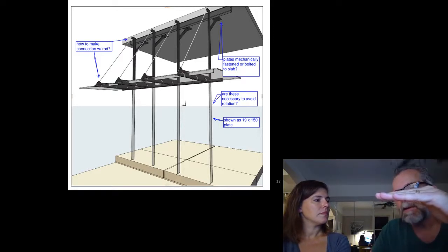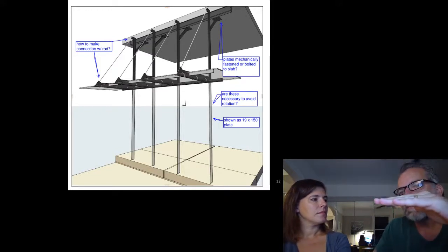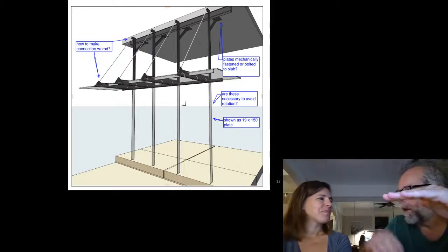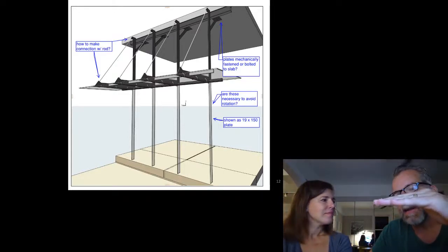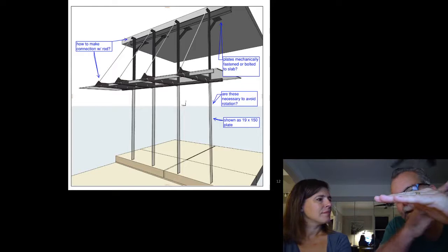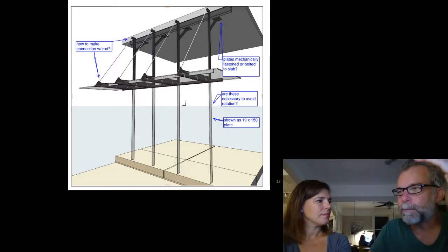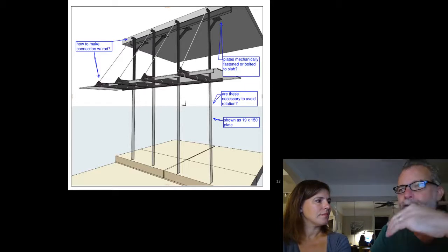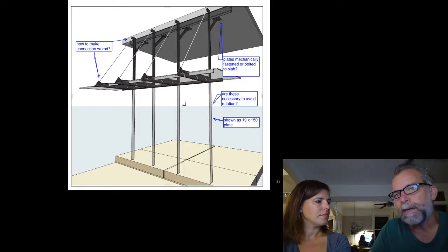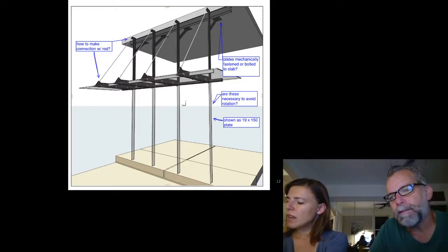Obviously you wouldn't do that on a glass canopy, but on a conventional canopy, to actually put weight on it as ballast means that you don't have to have a moment connection at your building, and that moment connection at the building can be problematic. If you're connecting to, for example, an existing brick and beam loft building, you can't realistically moment connect. But to ballast your canopy is